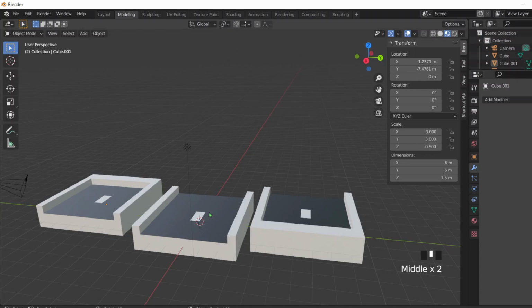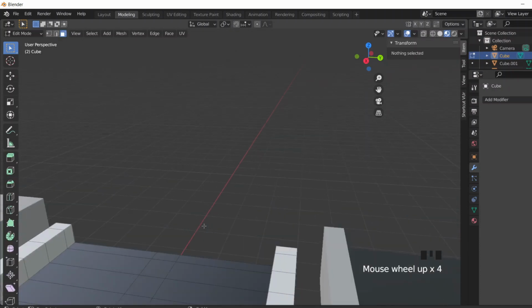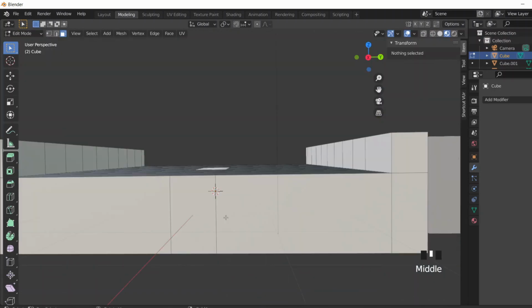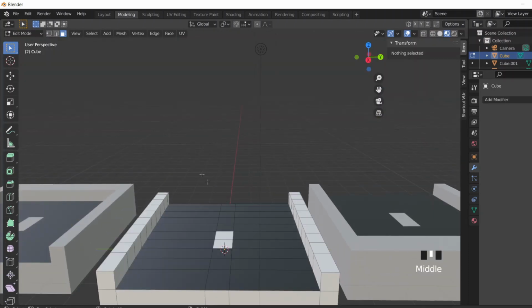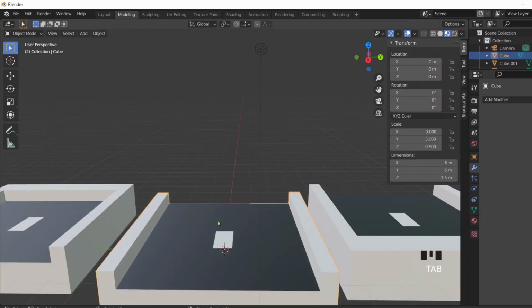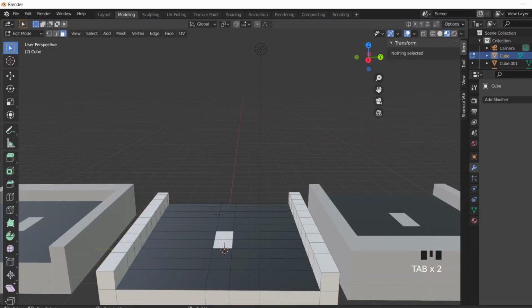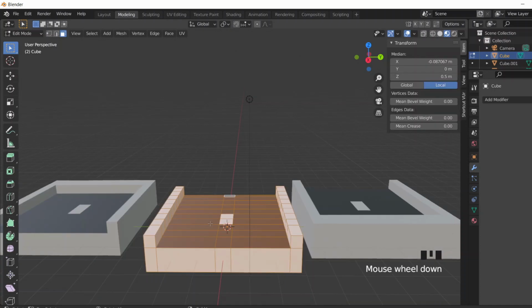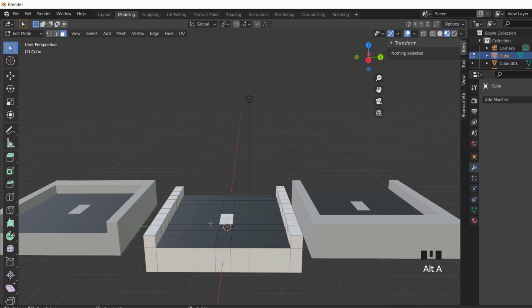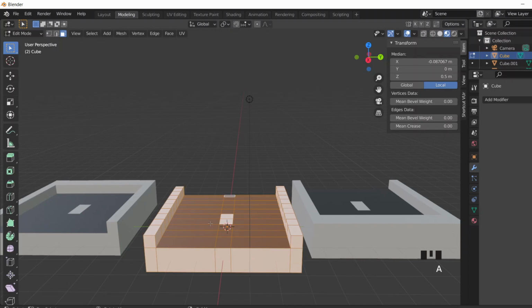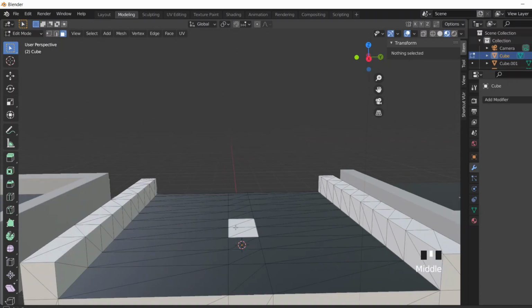Now that we have our 3 roadblocks, we're going to prepare these meshes so that they can be exported properly into our engine. And to do this, we're going to need to change the way that the edges are set up such that they're not squares but rather triangles. So if I were to go in edit mode, and I can do that by hitting tab and then hit 3 for the faces, and then just select all the faces by hitting A. If you want to deselect all the faces, you can hit Alt A. So Alt is the undo of the command that you write. So if you hit A, and then from here, what you can do is hit Control T. And this will essentially triangulate all the edges that you have in your mesh.